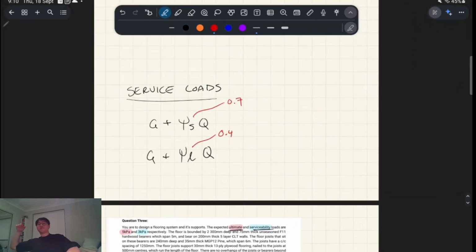So unlike before, instead of exaggerating the loads, we actually under-exaggerate the loads a little bit. This is because these service loads are everyday loads, like what you'd expect on a typical day for the service of this structural member. In the short term, you'd see a higher factor.